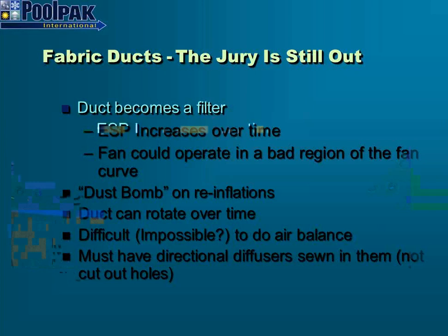In natatoriums where we're starting and stopping the airflow, we can have the dust bomb effect on reinflations. If they're not installed properly and fastened properly, they can rotate out of position over time and throw the air at some other place, in other directions rather than where it should be going, washing the walls and the windows.